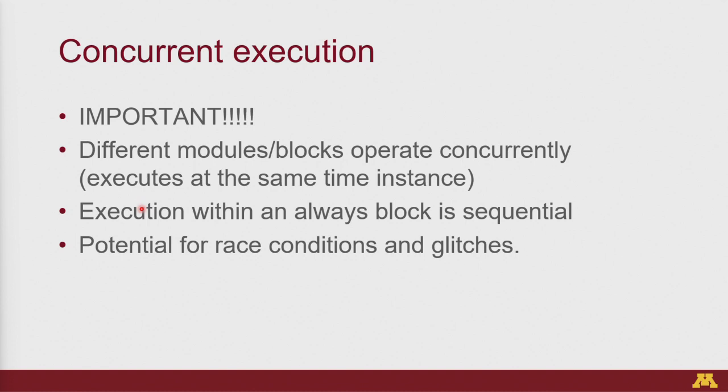The multiplexer is completely independent of the AND gate, and the AND gate is completely independent of the multiplexer. What that means in terms of code is that every line of your code is a concurrent operation. So the way you imagine that is that any line you write within your module or design, imagine would it still work if it was occurring at the exact same time as every other line, right?